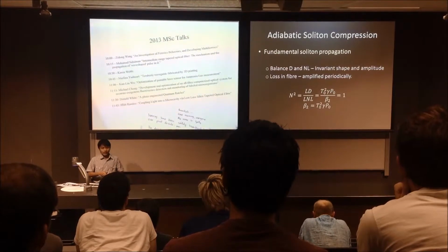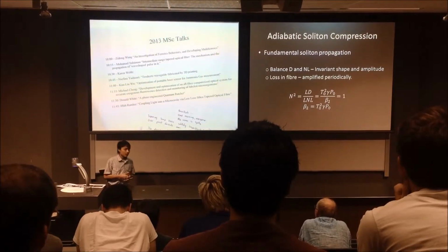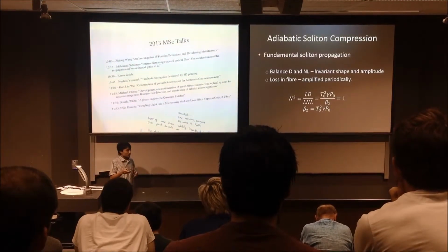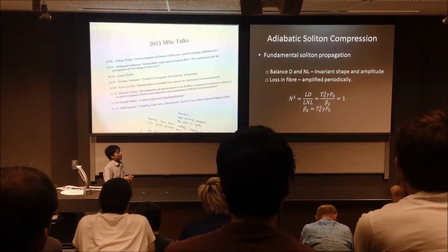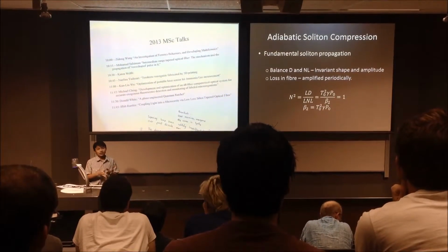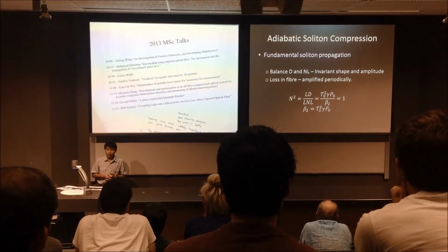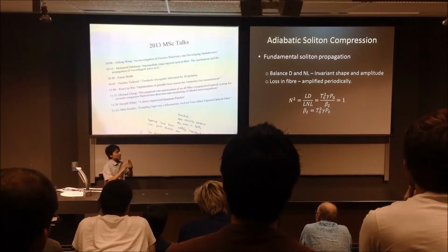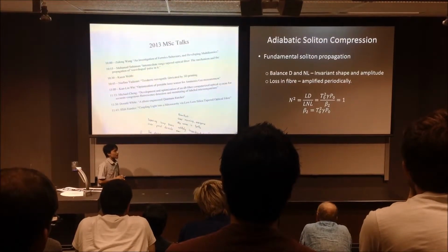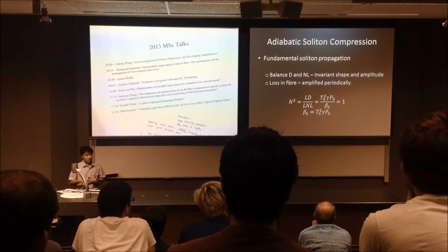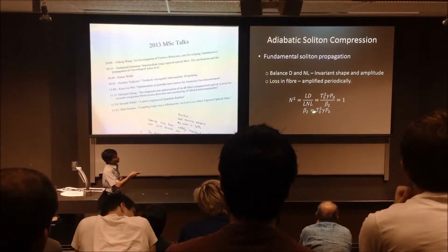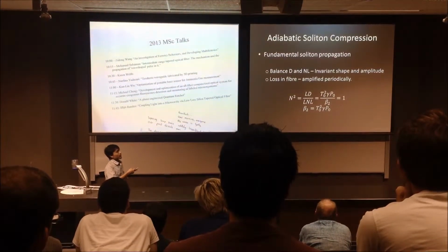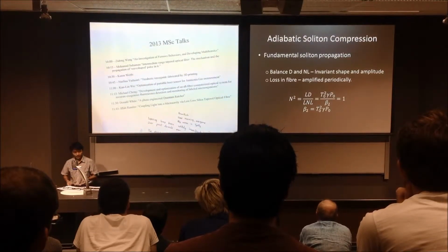The simplest fundamental soliton in non-loss fiber will maintain its energy, and so it will remain its shape and amplitude. And so by knowing this, when we alter beta 2, it will consequently result in a decrease in pulse duration.